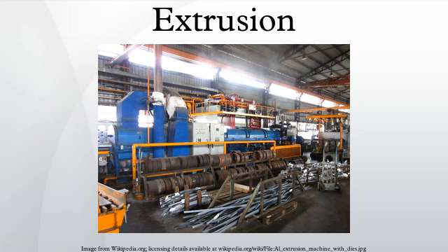A second advantage of this glass ring is its ability to insulate the heat of the billet from the die. The extrusion will have a 1 mm thick layer of glass, which can be easily removed once it cools.